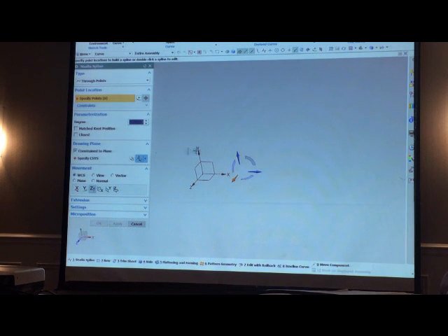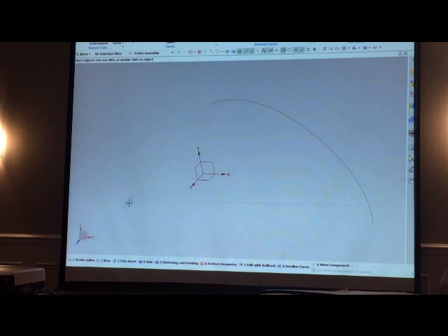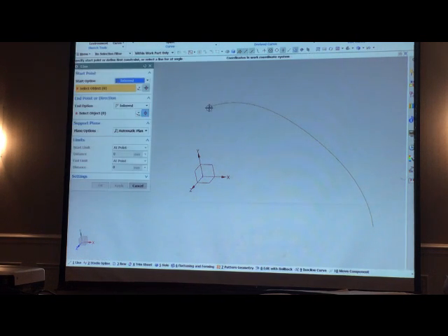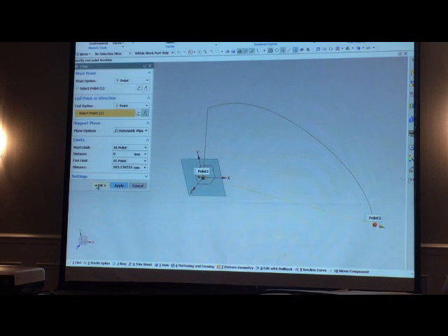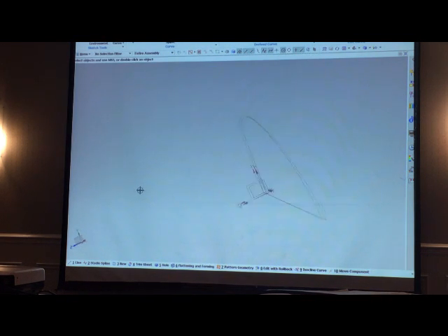So let's go in here, constrain to plane. So I'm going to pick that plane. I'm just going to draw a spline. Then I'm going to come in here and do a point to here, apply another point to here. So basically I've created a 2D profile without sketching. You know, see, there's a 2D profile without sketching. But I'd like to scale that now.